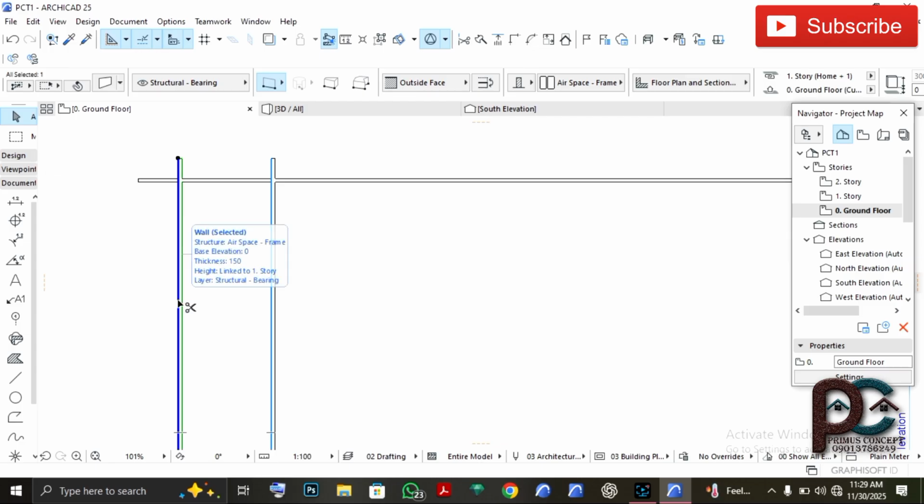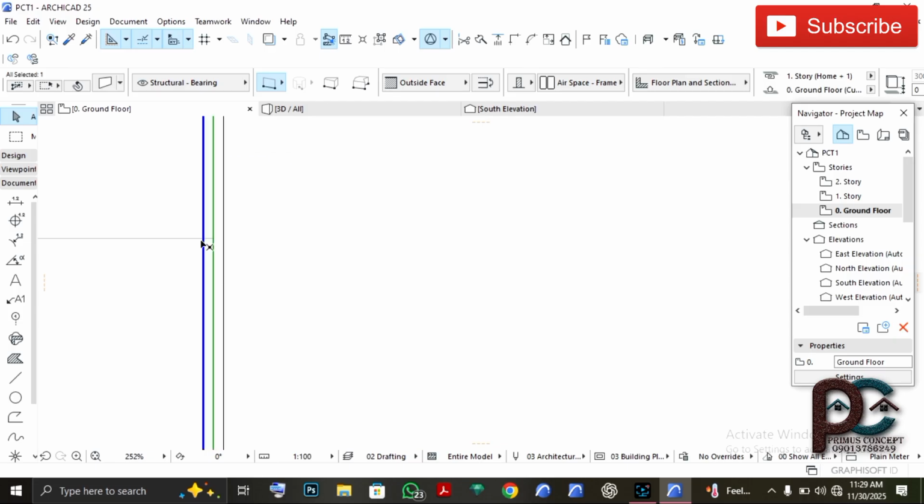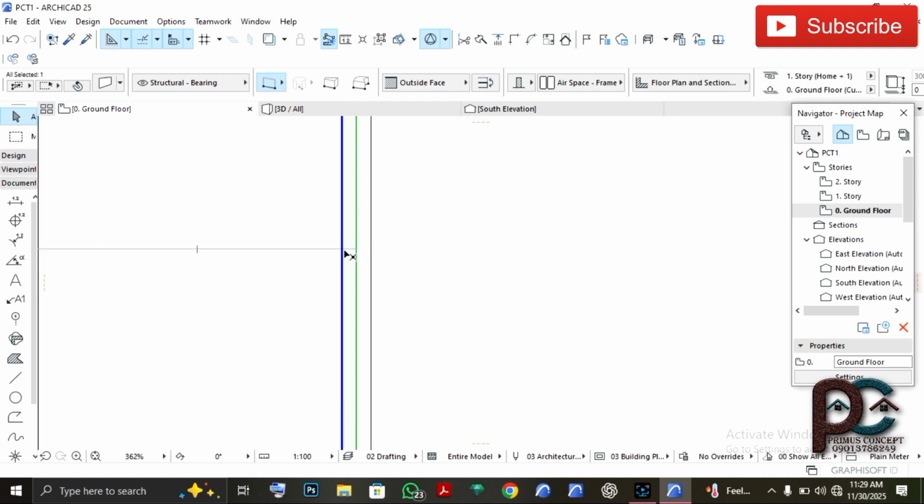If you do Ctrl+Shift+D, drag the copy, and you want to make the inside 3,300, let's do that, 3,300, and then we have it. You actually see that 3,300 enters the external wall of the building, so you have to shift again. So in that case, I normally add 150 to any dimension I make.